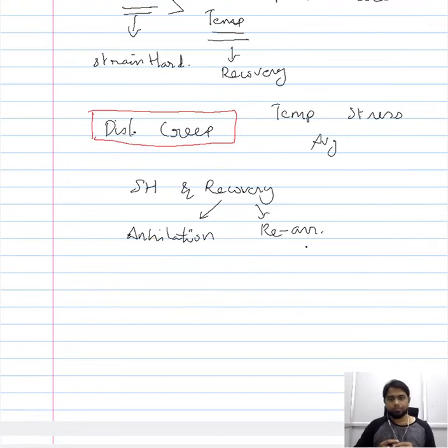Now we saw the rearrangement of the dislocation from say a horizontal arrangement to a vertical arrangement, thereby forming a grain boundary, or rather a sub boundary, that frees up a lot of space for the new dislocation to move, thereby enhancing the plasticity. This requires a special type of movement of dislocation called climb. So the amount of rearrangement depends on the amount of climb.